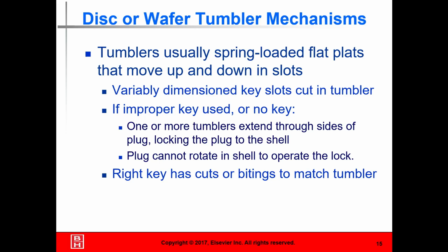With variable dimension keys, slots are cut into each tumbler. When no key is inserted, or an improper key is used, one or more tumblers will not be engaged, keeping the lock from opening.